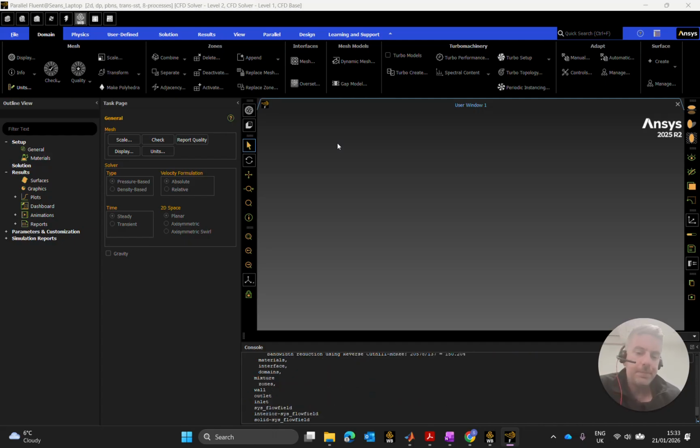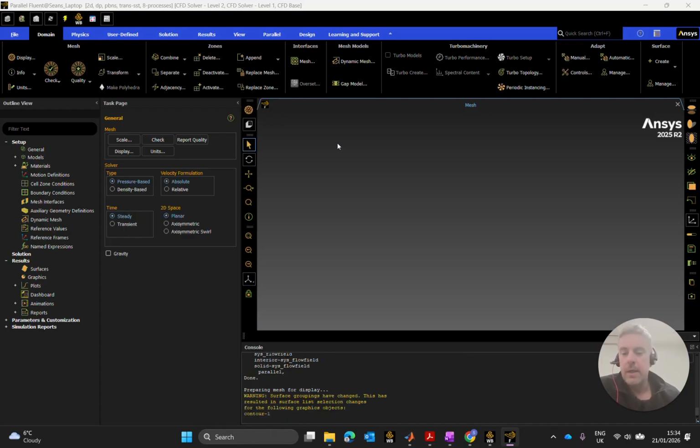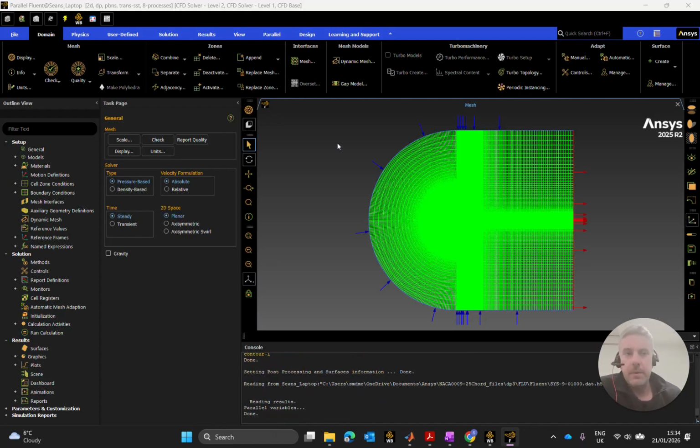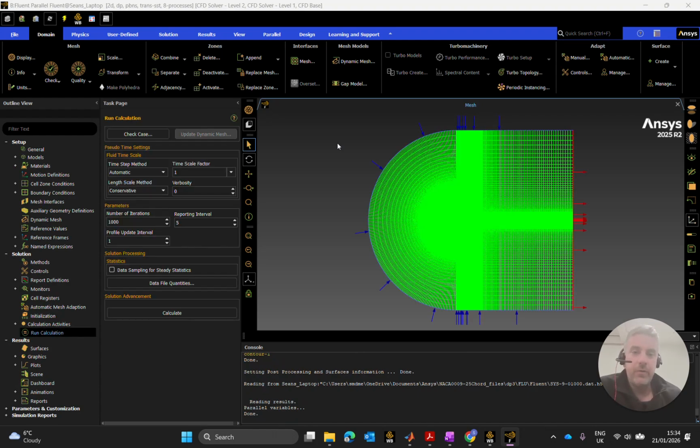Which brings up a good point when I say starting to separate: don't forget that we're running this as a steady state analysis. The laminar separation bubbles, and any of these external airflow problems, even at a 50,000 Reynolds number, which isn't huge, have transition regions in them. We should really be looking at this with a transient time step.